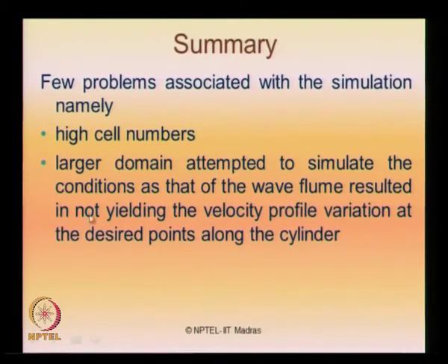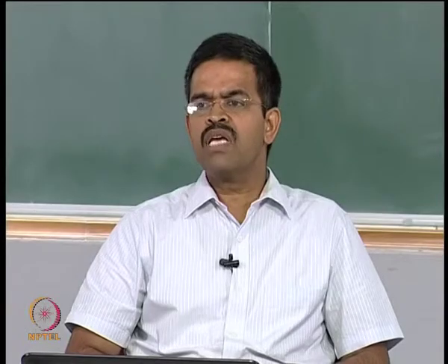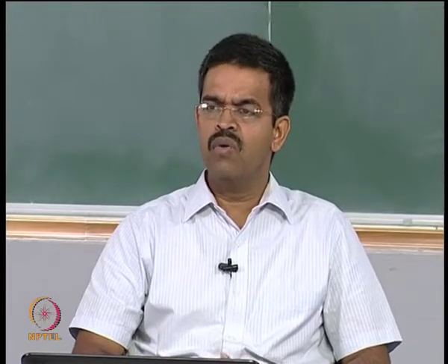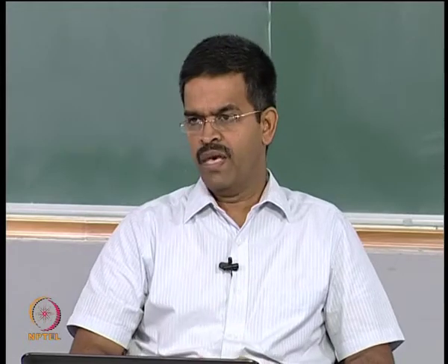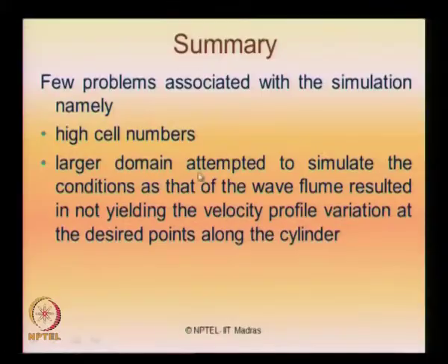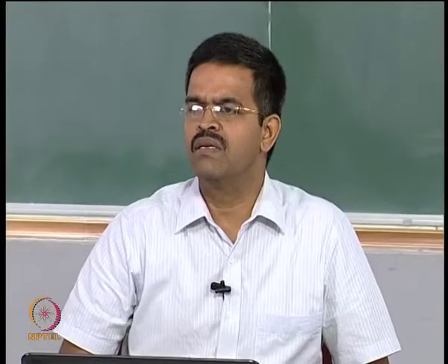This resulted in not yielding the velocity profile variation, because the interesting thing could be whether we can examine the velocity profile variation also. What we saw in the study now is only the force variation. If you really want to look at the velocity profile variation also, then the larger domain attempted in the study is not suitable, because it requires more data points along the cylinder if you really want to trace the velocity profile variation. These can be seen as a few limitations in the numerical study which we experienced when we compared it with the experimental studies.